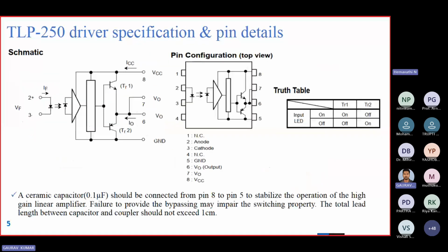Moving to the next slide. Okay, you can see this is the TLP250 driver circuit. There are a total of 8 pins: 1, 2, 3, 4, 5, 6, 7, 8. The 6th and 7th terminals are shorted. In the 2 and 3 terminals, we give the microcontroller pulse input.